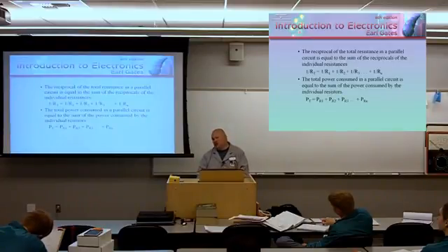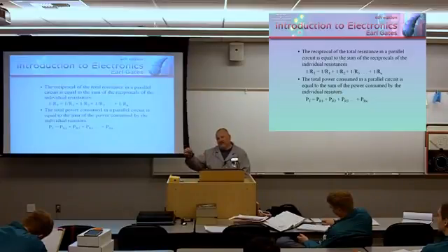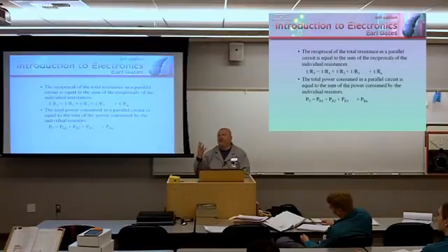Also with that, don't forget your thumb rules. Remember your thumb rules? If it's equal resistance, you simply count up the number of resistors, and divide the value of resistance by that number. If I have 4 100 ohm resistors in parallel with each other, what's the total resistance? 100 divided by 4 equals 25 ohms.